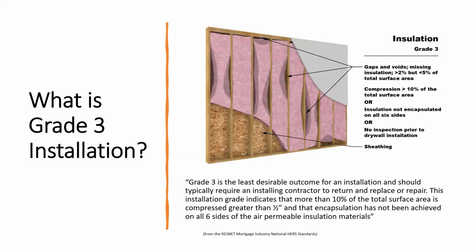So Cody, yeah, some confusion, all 6 sides, vertical application and horizontal, because GCLA has to touch subfloor, but not drywall in the garage. Yep. I mean, that's a good way of doing it. Yes, you're right. That does add some confusion a little bit. That's why we're looking for that R value. Is it correct? And is it in contact with the conditioned floor?